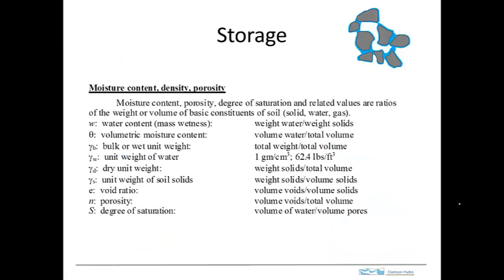When we characterize the storage of water in the vadose zone, we have several terms that result, and these terms are ratios of the different components. And to see how this works, let's take a look at this little sketch. If this is a representative volume of porous material, then we see at the highest level we have some solid materials and some pores, the material between the solids. And the pores are occupied in part by water, and in this case there's some pore space that's filled with air.